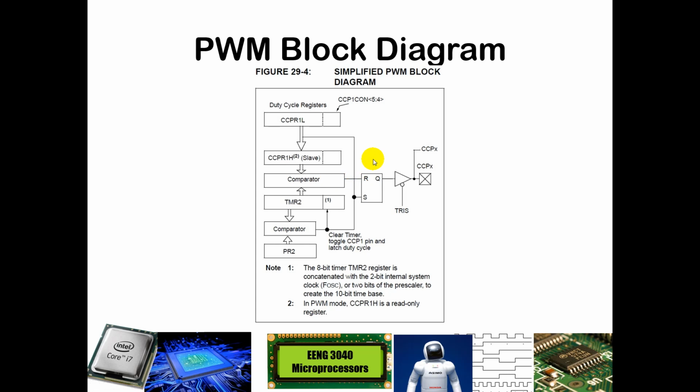And so in this case, if you have a 1 there, that is going to generate the falling edge within the PWM signal. So it will go to a rising edge later. We'll talk about when that gets generated, but it will have risen. It will delay so long as the timer is counting until it reaches the same value as is in this 10-bit concatenation of CCPR1L and CCP1CON. Once it is, it will then reset it.